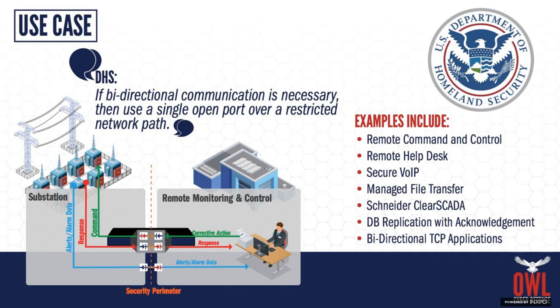That's basically what is happening with this solution. You're allowing a TCP/IP connection to make a round trip. It's being verified, it's being limited. You can only initiate that from the inside out, so the connection would not be able to be initiated from outside the facility. And then only a very specific traffic thread is allowed through, a single port, and you're whitelisting and locking down all the potential things that you're connected to.